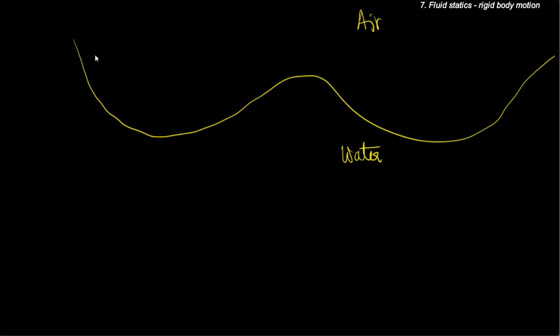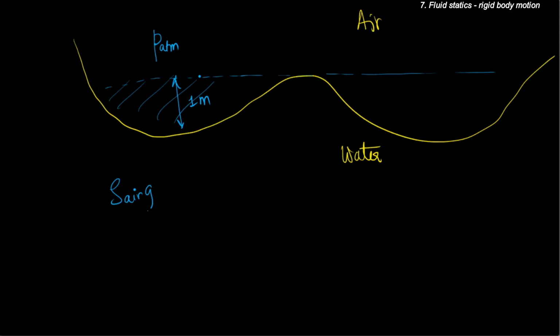But atmospheric pressure acts equally at all points, meaning, okay, first of all, let us assume that these differences in altitudes are not humongous. They can be at best 1 meter, 2 meter, doesn't matter. So the added pressure on top of the atmospheric pressure because of a column of air that is 1 meter high will be negligible. So the pressure contribution rho air g h is negligible as compared to P atmosphere.